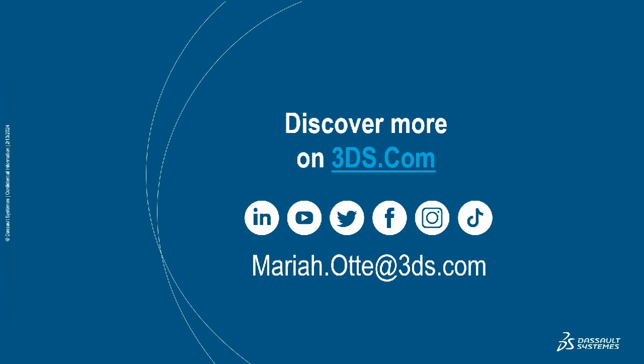There's the robot library, which DS R&D goes through every once in a while and refreshes, and I think I've seen Motoman in there. If it's not in there, you would have to import the solid model and then define all of those joints and the limits associated with them, both motion and speed and acceleration. So you can pull anything in, it's just not going to automatically generate it based on its data sheet.